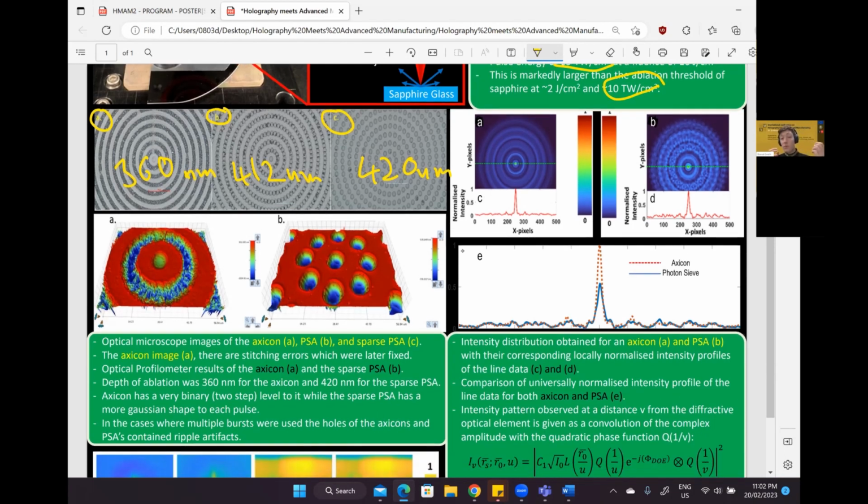Well, there's a relationship between the thickness of the device that you want, the wavelengths that you want to interact with, and the refractive index of the material. So we wanted to target 600 nanometers of light for imaging purposes. And if you put that into the calculation, you get that you want your depths to be about 300 to 400 nanometers, which is what we have done.